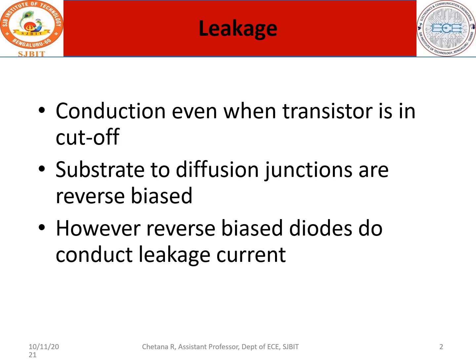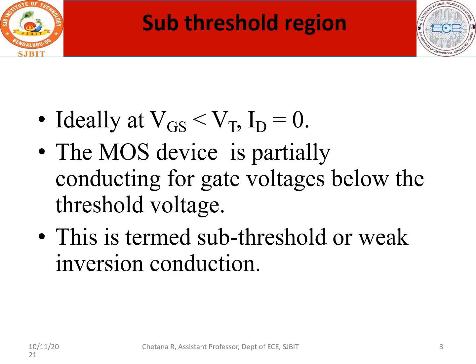Actually, the junctions which are present in the substrate should not conduct, but the process of conducting is called leakage. We have something called the subthreshold region. Even before the device reaches the threshold voltage, the device starts conducting, and the region before the threshold voltage is called subthreshold, because threshold voltage is the minimum voltage required for the device to go into the on condition.